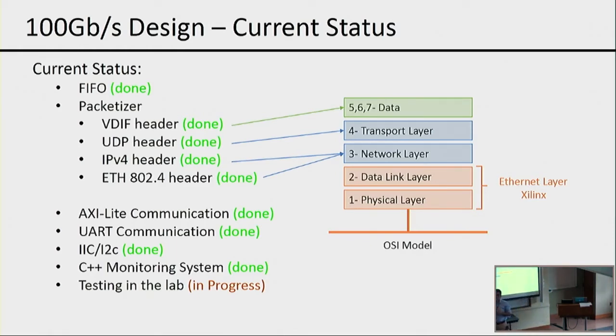So we only transmit data when the IP is ready to transmit data, and the data is constantly coming. So if this block cannot receive any data to transmit, what should happen to that incoming data? So currently we drop the whole packet. So it's in the FPGA. It's not even before creating or transmitting the UDP.